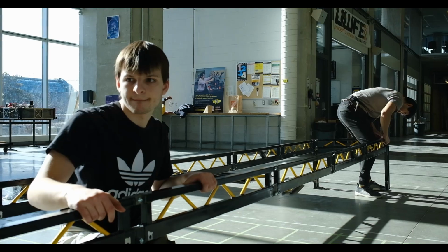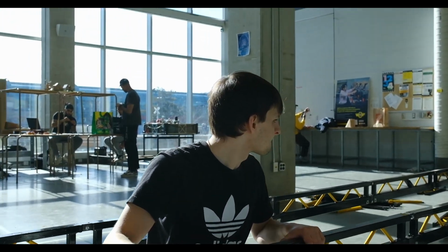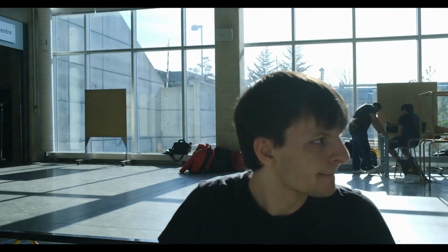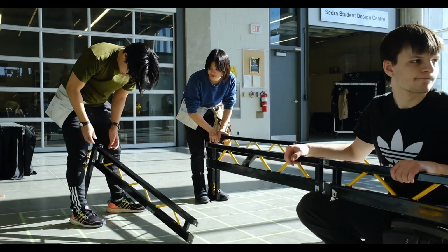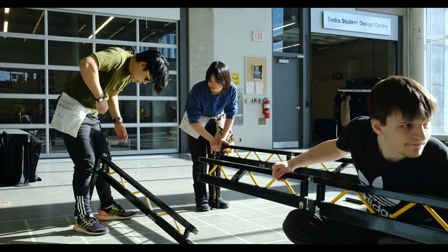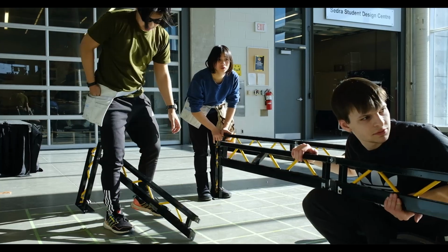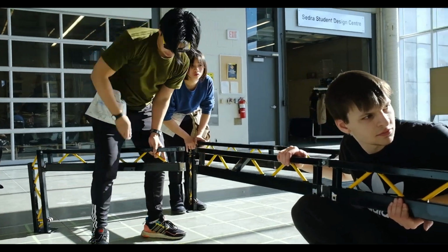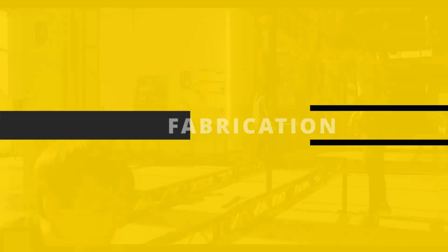Our construction process takes place with 2 builders on one side of the river, 1 on the other side, and 1 in the middle, which helps make connections over the river easier. The builder in the river assists the solo builder. Some pieces needed for the main truss are passed over from the other side of the river to the solo builder via the river builder to prevent them from having to let go of the structure. Once the first side of the bridge is installed and is standing freely, builders on both sides are able to assemble the under truss in a similar process and then finally add the lateral members.